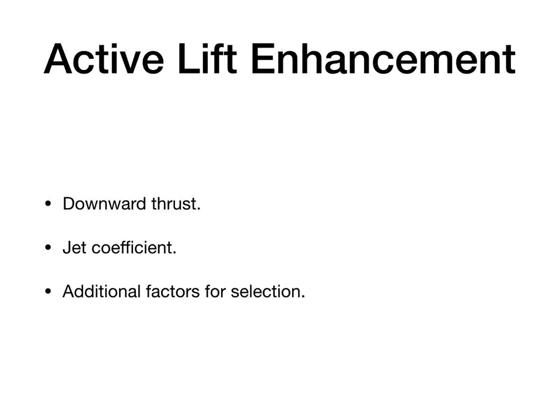The effectiveness of these active approaches is summarized in terms of drag polar, that is CL and CD. Any of these is capable of providing a lift coefficient in excess of 7.0. The vector thrust, USB and IBF have lower drag coefficient than EBF, externally blown flaps. Also, the effectiveness of USB is a function of a jet coefficient defined by the ratio of thrust divided by q times SW.